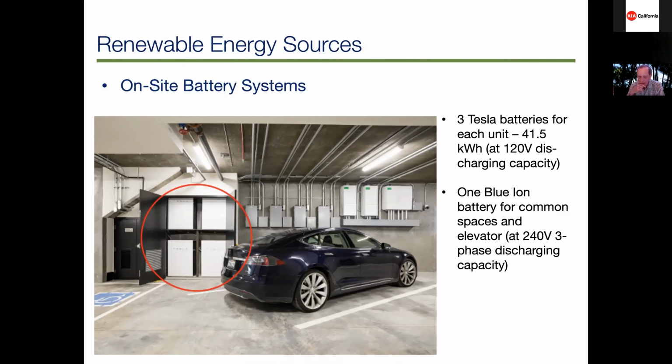So basically, these units, I haven't talked to the developers since the wildfire last year, but I would assume that everybody had perfectly good air inside if a filter was attached to the ERV, getting the fresh air. Of course, it doesn't do any good if you're bringing in ash through that system. So you have to have a filter on the outside, but I'm sure they've done it by now. Anyway, with power down, they kept functioning. So everything was in place for them to be very self-sufficient.